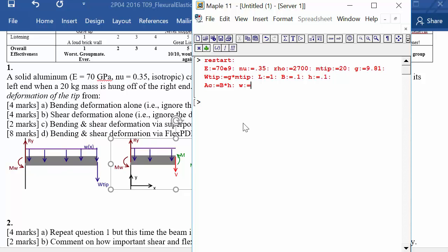So we can get the weight per unit volume: the mass per unit volume is the density rho, and multiplying by G gives you the weight per unit volume, rho G. Now we're going to multiply that by the cross-sectional area, and if it was per unit volume, we've multiplied by area, now it's per unit length. If you were to then multiply this by the entire length, you'd have the total weight. So as it is, it's the weight per unit length.